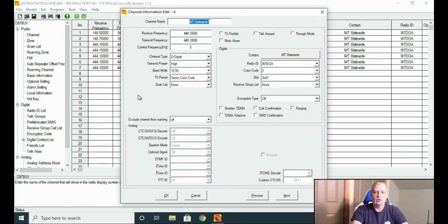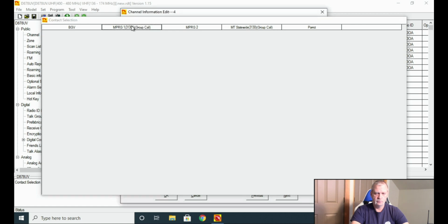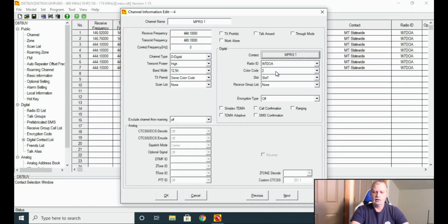The second one, I will go back into it. We're going to change this to MPRG1. I'm going to leave everything the same except I'm going to change the talk group there, and then MPRG1 needs to be on time slot 2, remember. So we will change that to time slot 2. This channel is done. We can go next and go to the next one. This one will be MPRG2. We will change the talk group.